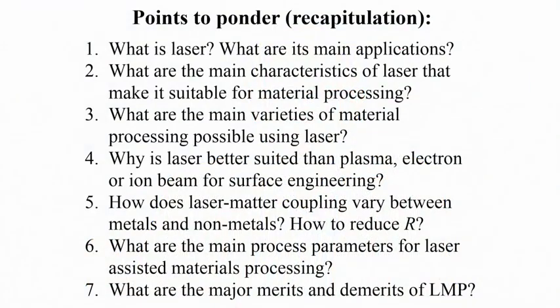There are two main variables we are talking about. One is the interaction time, the other is power density, and by varying these two parameters we can cover a very wide range of materials processing. We always consider laser to be a better suited agency for material processing, particularly surface engineering, than plasma, electron and ion beams, because of the exponential nature of the decay profile of the incident energy.